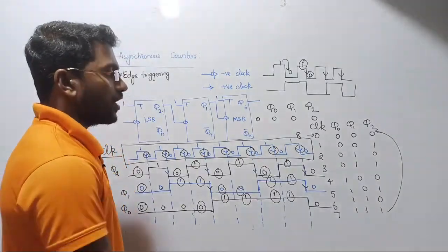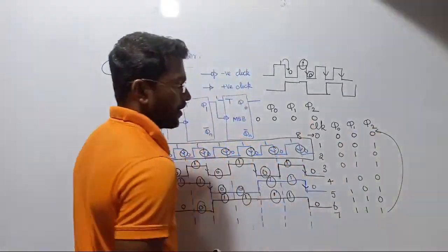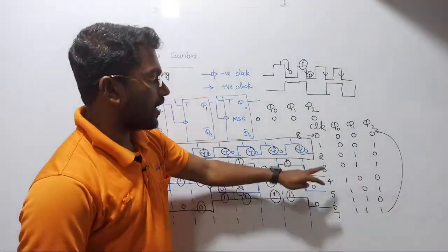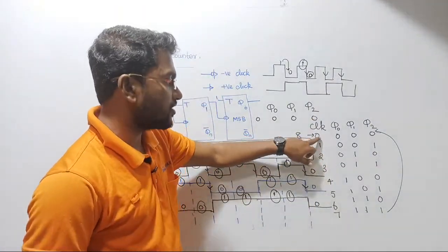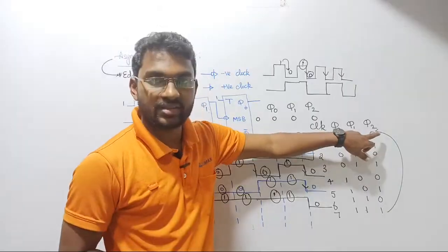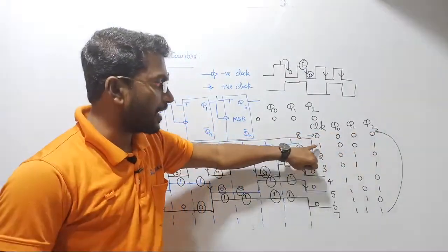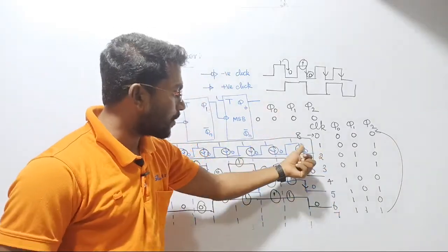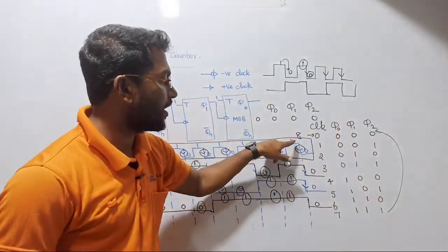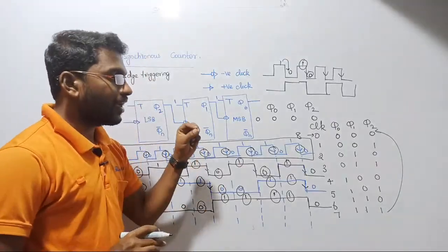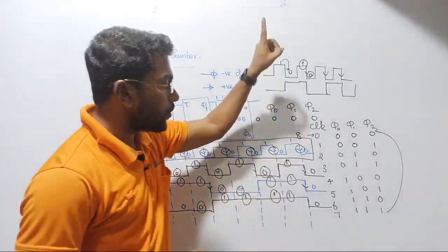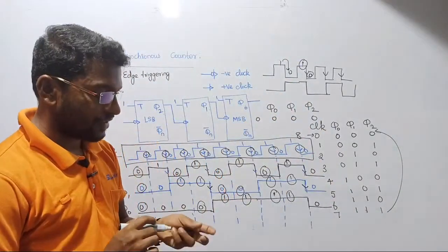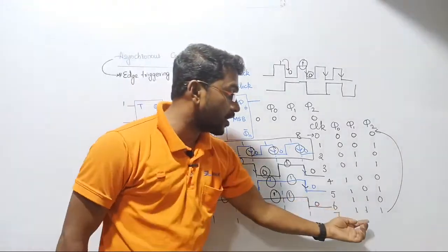So in order to complete one complete cycle, see there, I have just started from 0. This is the initial state. Without applying the clock, I was standing here. In the first clock, I started my journey here. I was running up to 7. Exactly at the 8th clock pulse, we are getting back to the original state. Clear? So totally, 8 clocks are required in order to complete one complete cycle. Guys, listen. At the 7th clock pulse, you are standing at 1, 1, 1.